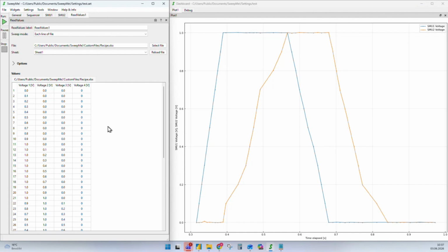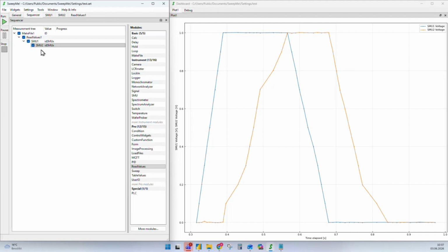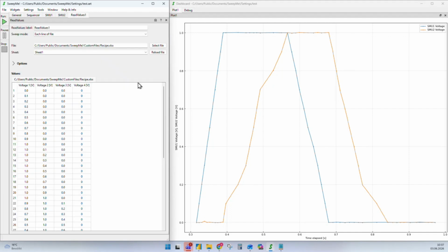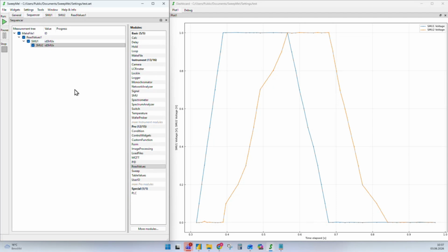And then you can hand over these positions to a robot, and you can create a certain path the robot is moving. And if you combine it, for example, with other equipment, you can hand over some of the variables to a robot and some of the variables maybe to other equipment like a syringe pump. And you can build a dispenser robot with this module and the robot module and the other equipment. So basically, you can load and read values variables for different modules and can hand them over also to different modules, not just to this single instrument, but can be a combination of different instruments where you want to synchronize a certain process that is running through.